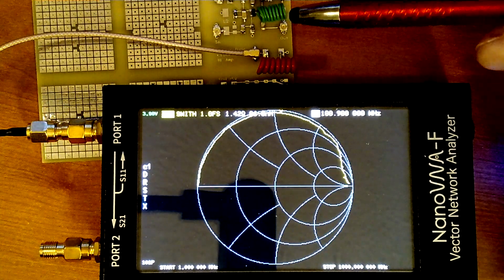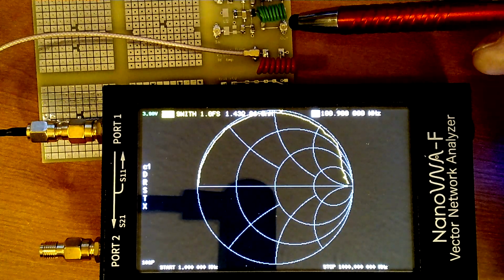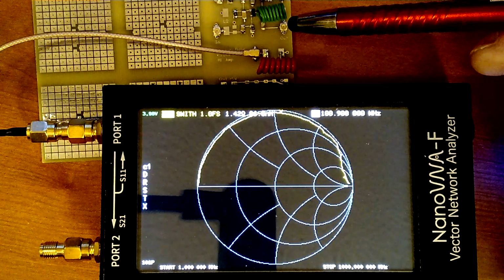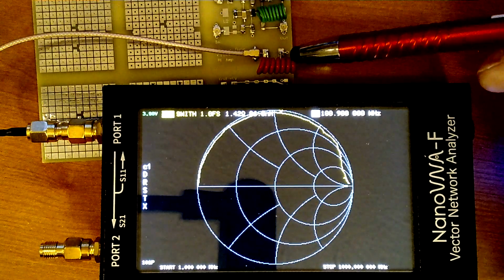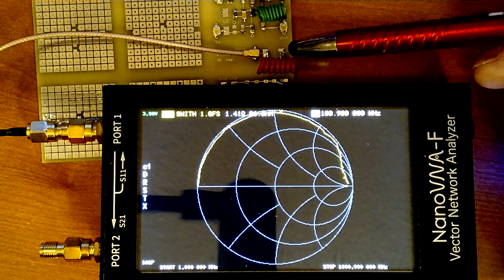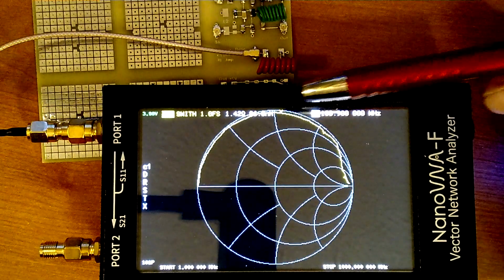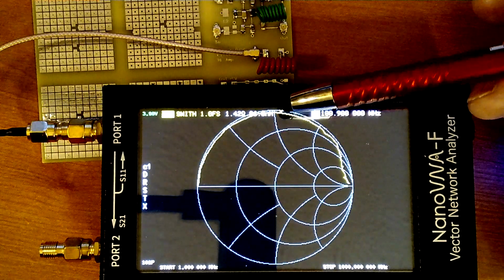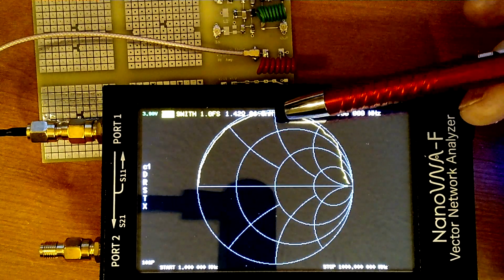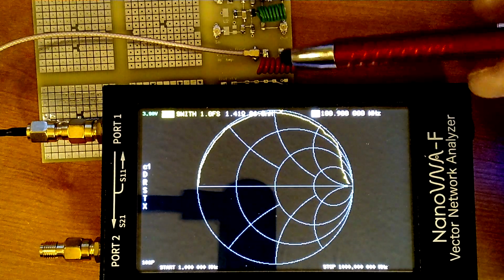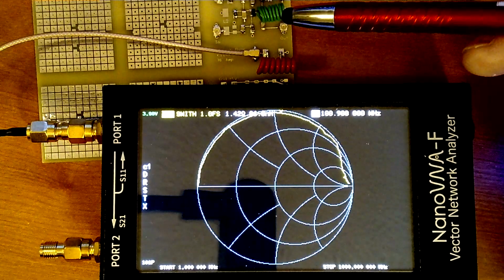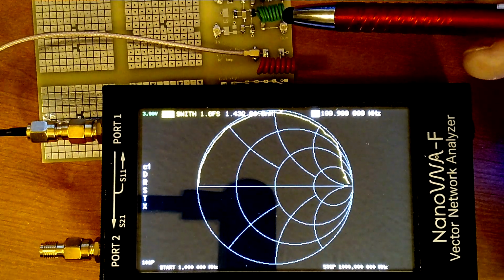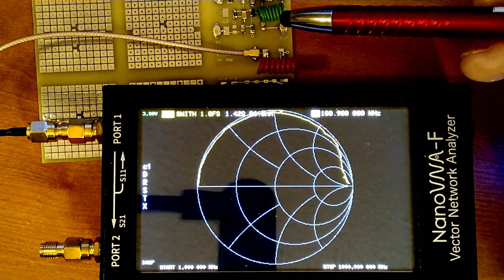In this RF amp design, which is intended to work in the FM broadcast band around 100 megahertz, I needed an inductor of 150 nanohenries, so I wound one and I put it on the test jig here and measured it, and it came out to be 86 nanohenries. So it was not high enough, so then I got some smaller wire and wound that, and I got one that was about what I needed. And then I just stretched it out to make it exactly 150 nanohenries.